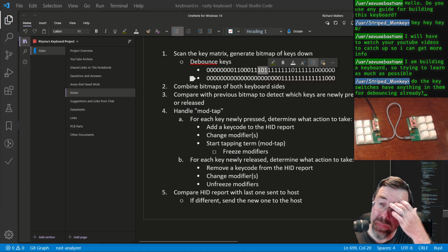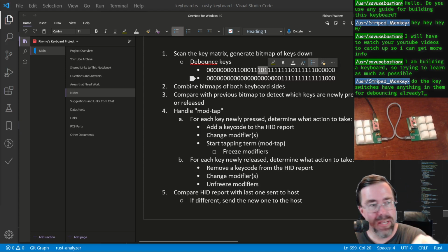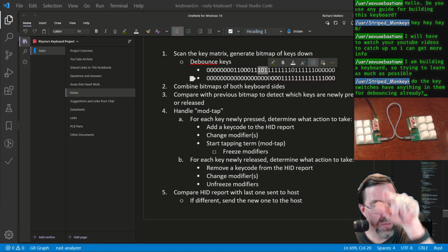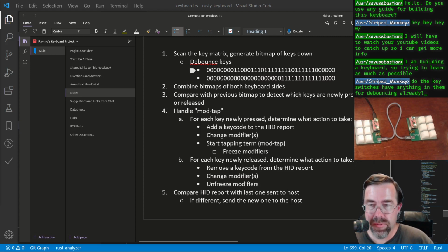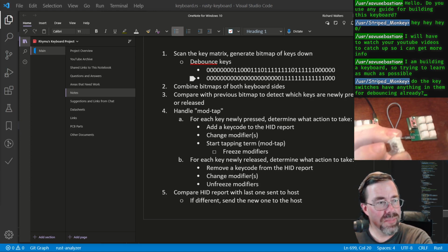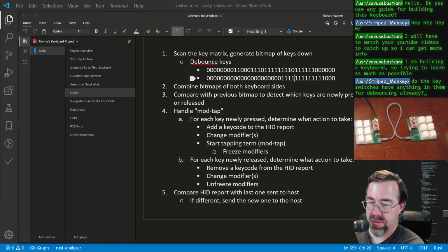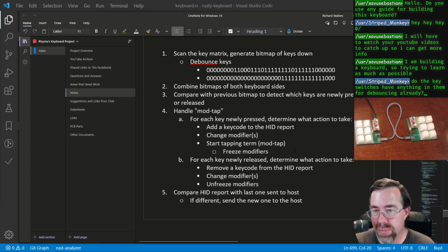But there's also electrical bouncing where the signal is not exactly square, but there's some ringing in it. And depending on how bad the ringing is, it could be detected as a 0 where it should have been a 1, right? So both kinds of bouncing can happen, and we want to try to eliminate both. And these switches, although they're mechanically making it less likely to bounce, there's still some bouncing that we see. It's probably not as bad as if it was a plain, simple plunger and plate up underneath it.